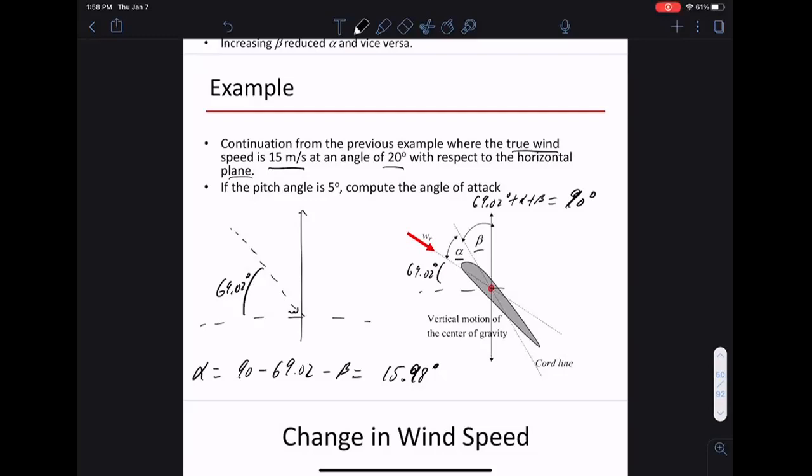Is it because the angle of the wind can always be changing? Can always be changing, but sure. But then that means, right? Normally when you change the angle of attack, you change the lift. So if the angle of wind changes, then at the same beta, the lift can change, right? So it's not as if one pitch angle will correspond to one lift or one power generation.